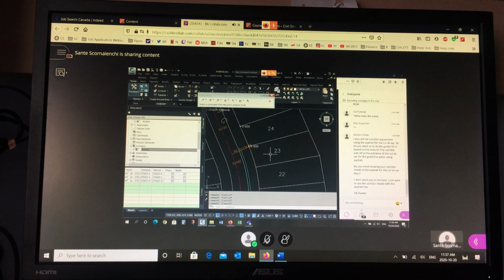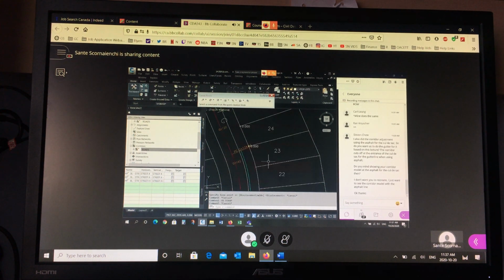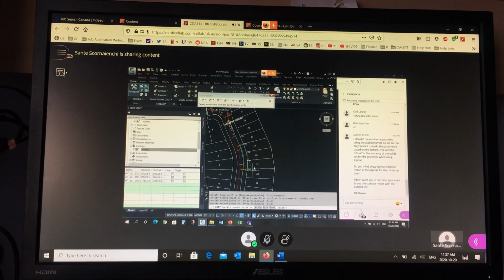Once you create one point, you can create a copy of it. So I'm going to grab this. Turn your O snaps to end point. Once you create one, you can create a copy, end point. Turn this on so that it knows how to sequence it. Number, endpoint, endpoint, endpoint, go all the way around, all the front lot corners. That's on one layer, in one group.